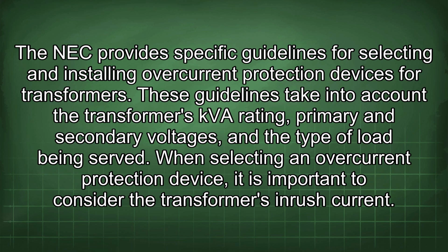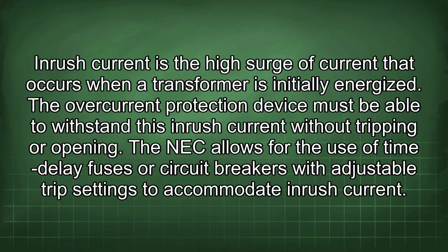When selecting an overcurrent protection device, it is important to consider the transformer's inrush current. Inrush current is the high surge of current that occurs when a transformer is initially energized. The overcurrent protection device must be able to withstand this inrush current without tripping or opening. The NEC allows for the use of time delay fuses or circuit breakers with adjustable trip settings to accommodate inrush